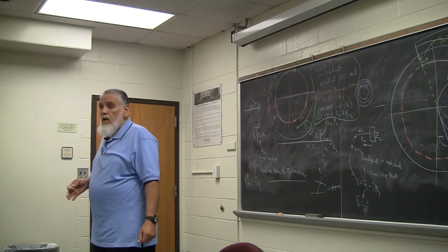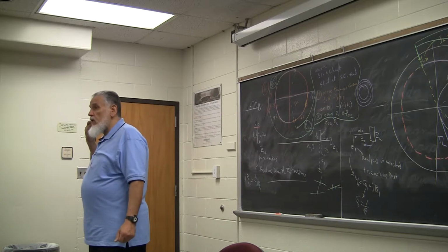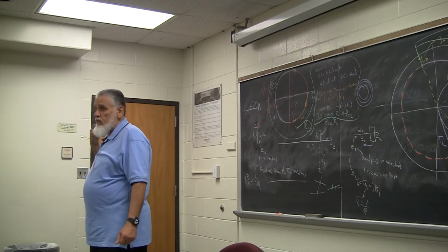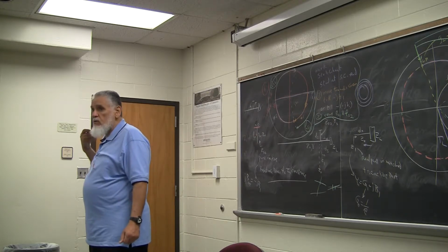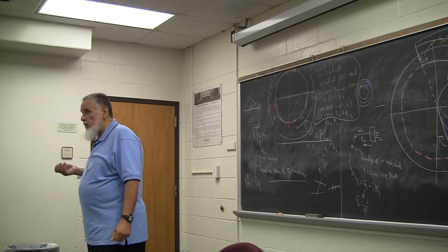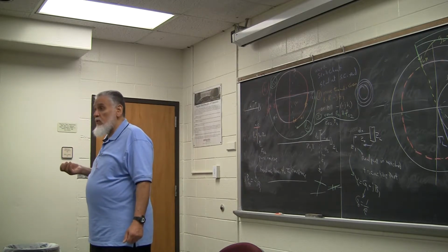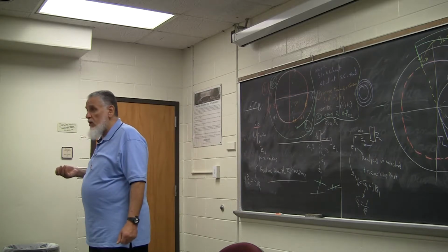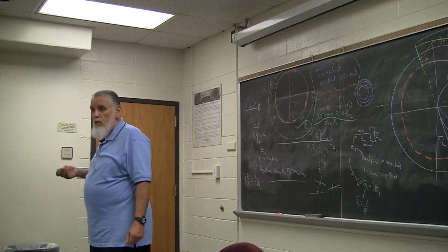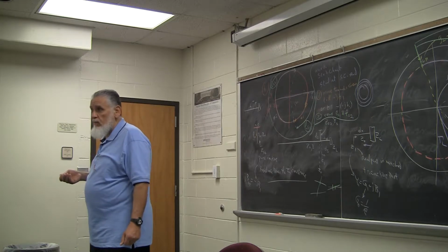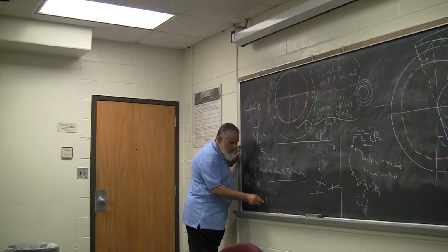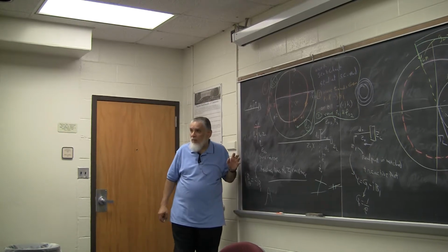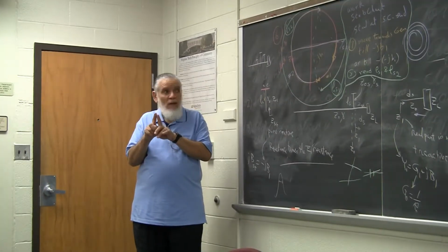Okay. Now, supposedly, these kind of circuits are not resonance circuits. The kind of situation that we have here is not exactly a resonance situation that we worry that much about Q. Nevertheless, Q is a very important factor when you design tuned circuits. Basically, if you have a tuned circuit and you have a filter, Q defines the bandwidth of this. So the higher the Q, the narrower your bandwidth.